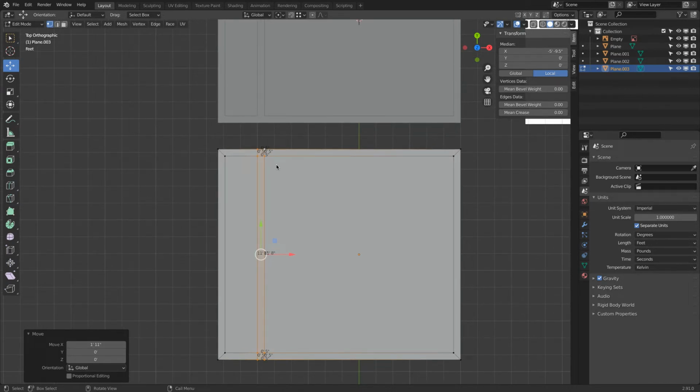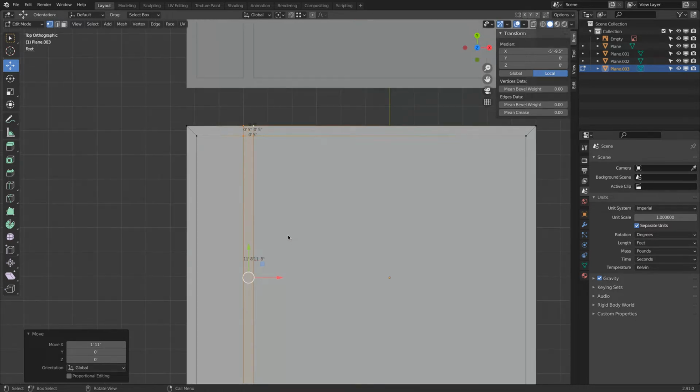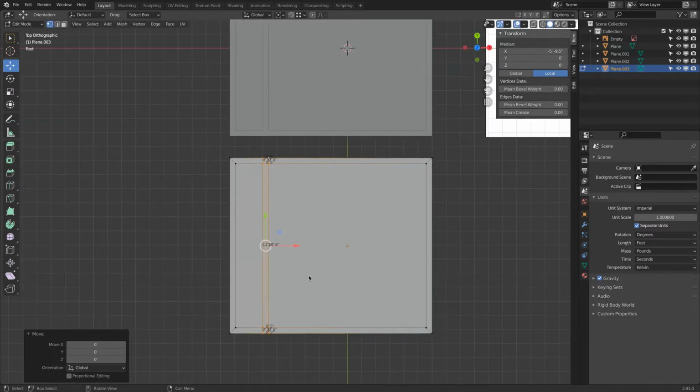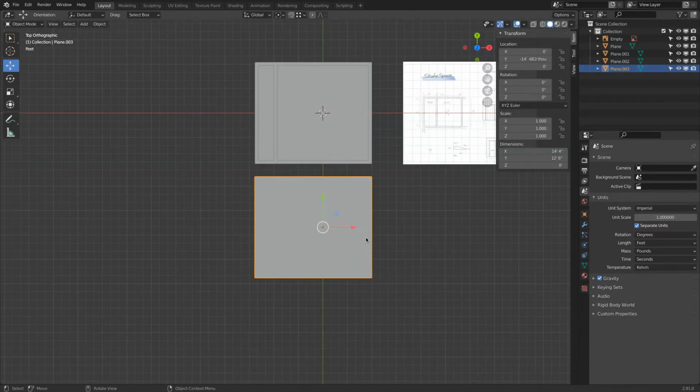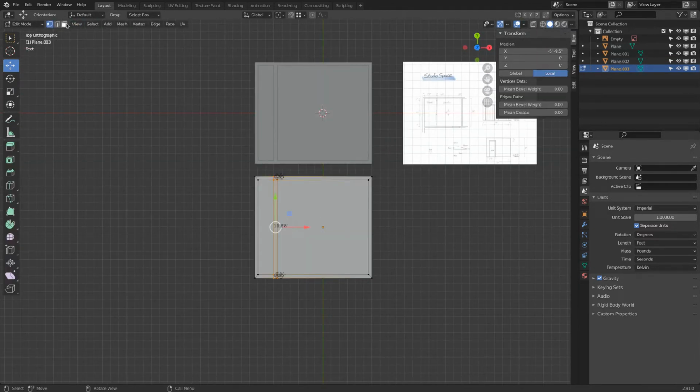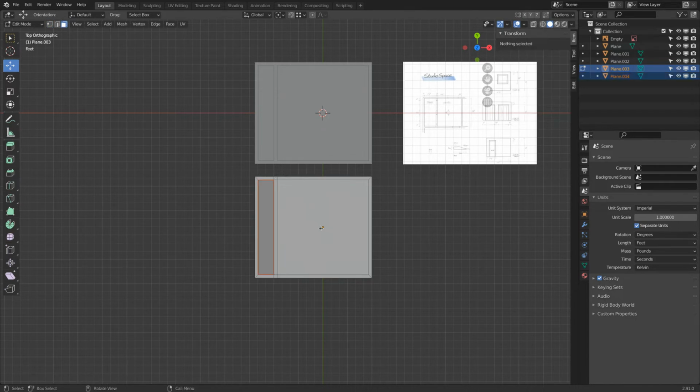In architecture modeling, nothing is precise to a millimeter. Walls are not really perfect. So the second method, which I showed you right now, is actually more precise. But honestly, if you ask me what I would do, I would just simply move it and then pay attention to when does this read out as 1 foot 11 inches. Done. Okay, very nice. So the last step we have to do now is select this rectangle and separate it.